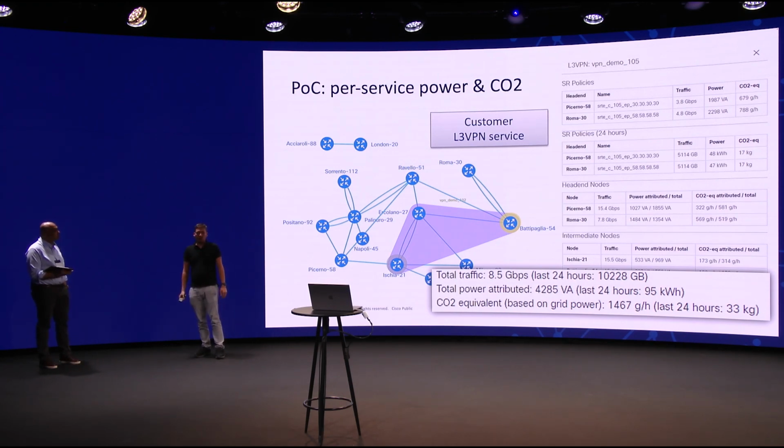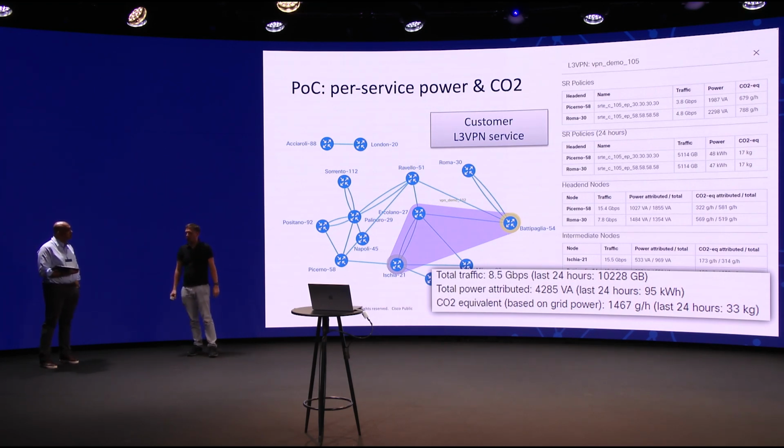And so if we have this value, grams of CO2 per kilowatt hour, we can just multiply it with the kilowatt hours consumed by the device, and that way get a carbon impact of the device, assuming we are using grid power. Of course, if you have additional power sources, then you need to factor this in as well. And we also didn't take into consideration the AC power, but you can always make it more complex.